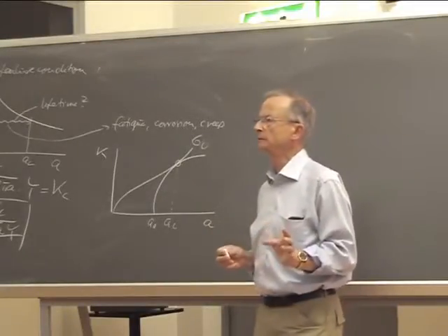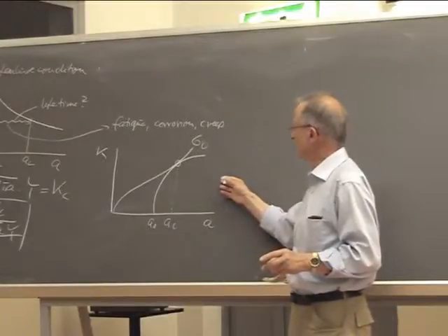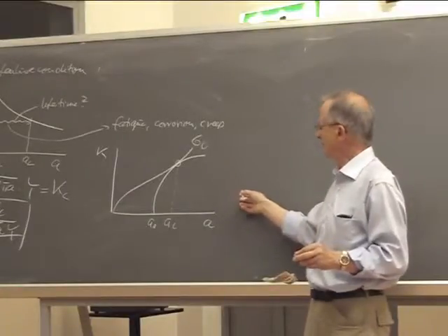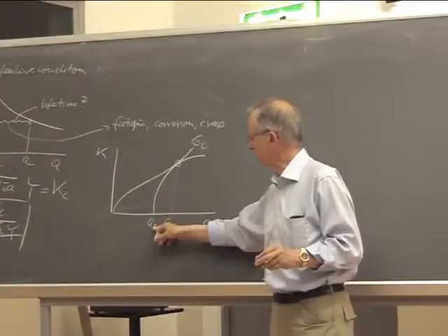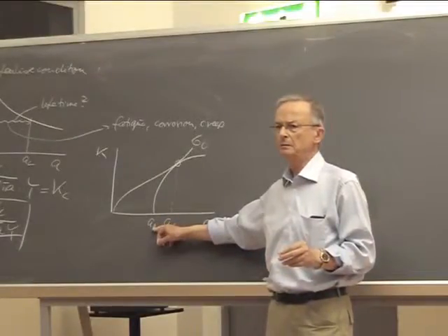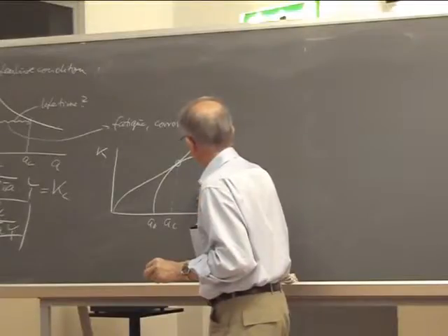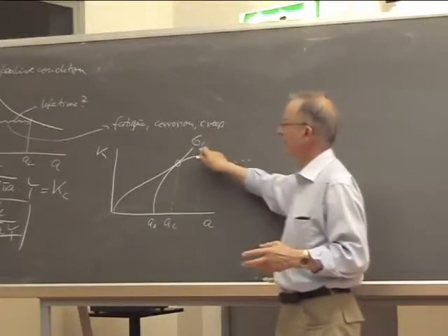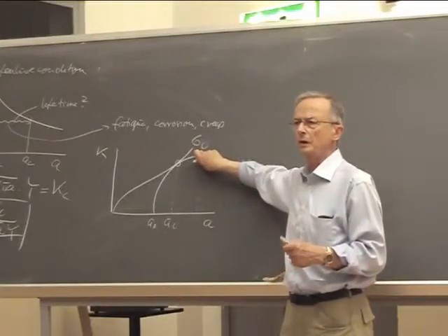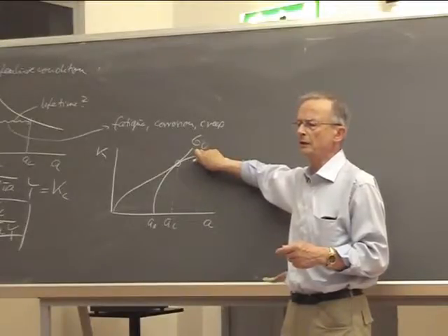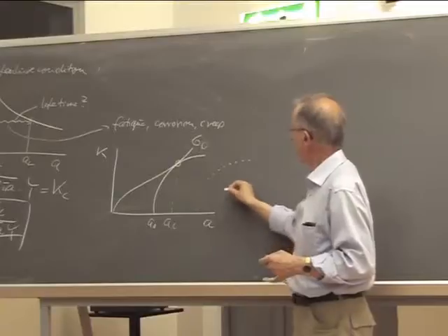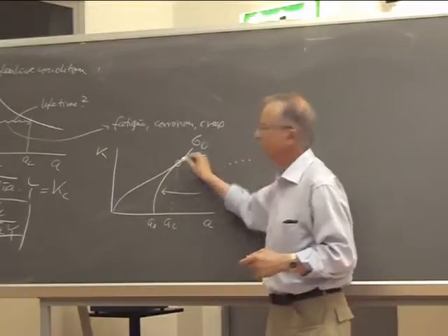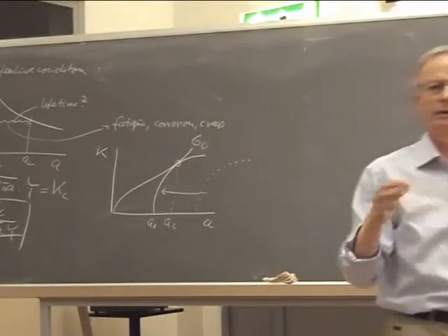There's another thing. We can use the same construction if we ask what is the crack size I have to find. So in my mind I have the R-curve and I have the applied stress. I draw this line here, the critical applied stress line. And then I shift the R-curve far enough that I reach the tangency condition. So, you can play around with these things.